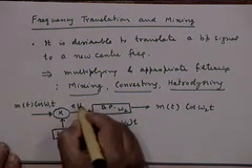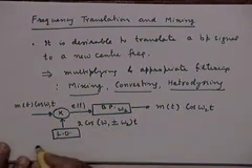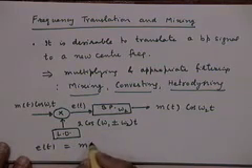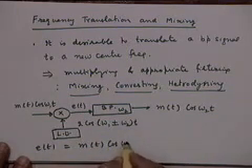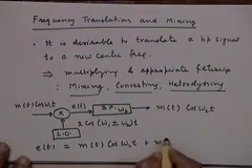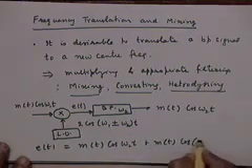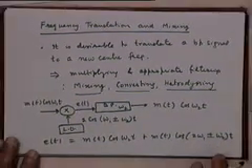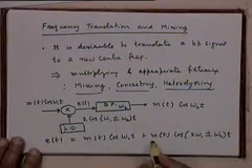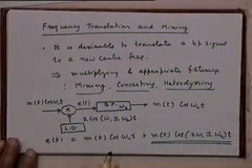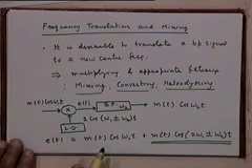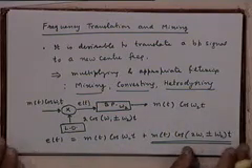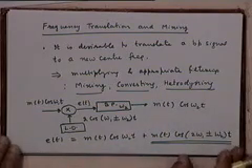So this signal at this point, basically the theory is that if you look at this signal e(t), this you can write as m(t) cos(ω2t) plus m(t) cos((2ω1 plus minus ω2)t) through the trigonometric identities, right? And through the bandpass filtering you are eliminating this component, retaining only this to get this output. So this process in general is called mixing.